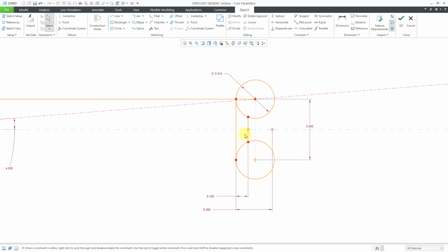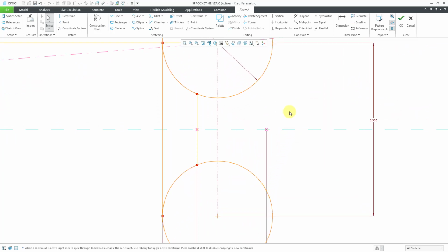And so this little segment in here, this is going to end up being one of our main regions that we use for extruding the shape of the tooth. But anyhow, let me then go about. So let's see, we're also going to create another line, and this other line is going to be a width of 10% of the pitch. Let me zoom in over here.